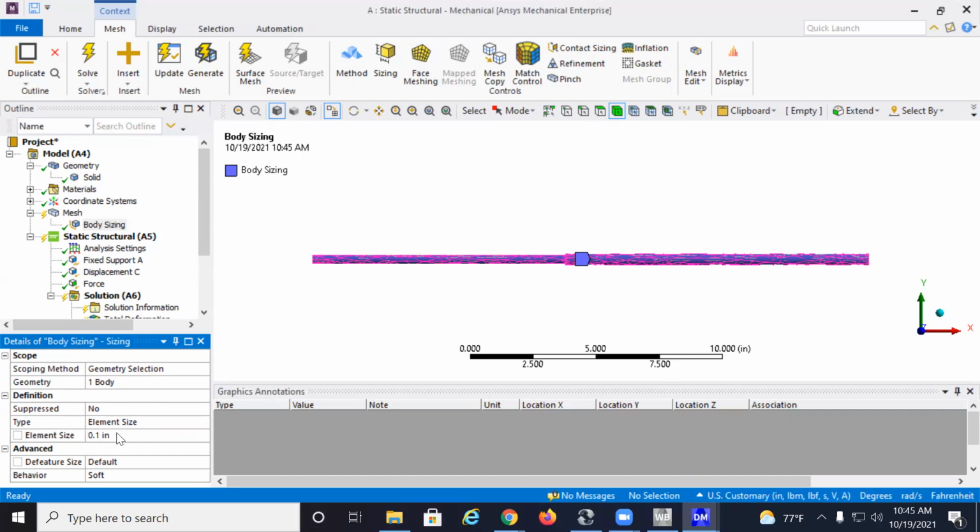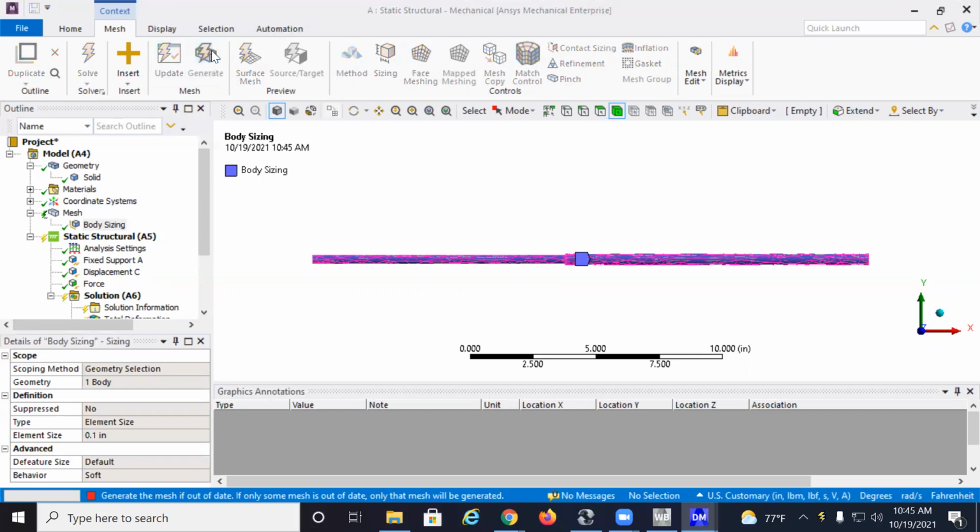This is going to force the automatic mesh generator to use smaller size elements. Of course, if I use smaller pieces, I can better fit them within the geometry to still keep the geometry more or less as we like it. Now, you see the flash icon. Because I changed my mesh, I'm ready to regenerate or create a new mesh. So I'm going to go generate.